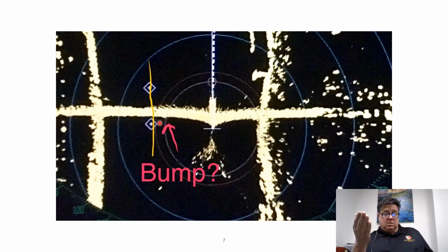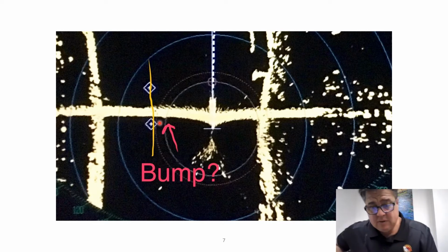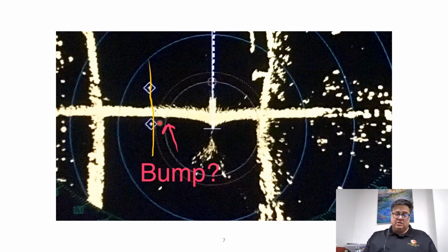The radar could be operating in a different datum from the AIS. The AIS is coming out in World Geodetic System 1984. Typically WGS 84 is usually the datum set. Maybe the radar isn't in that datum. Or the radar is in a Cartesian coordinate and it's not in a spherical datum. So there might be a datum shift issue in where the radar thinks the latitude and longitude of an object is relative to the radar picture. Or there's even other things.